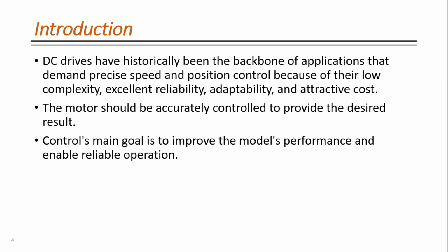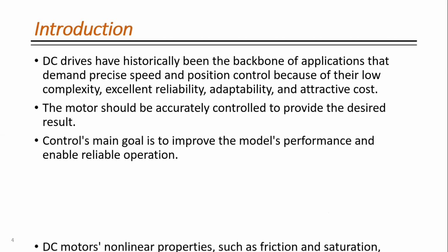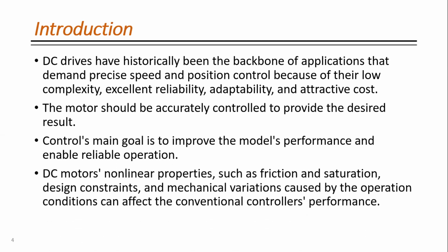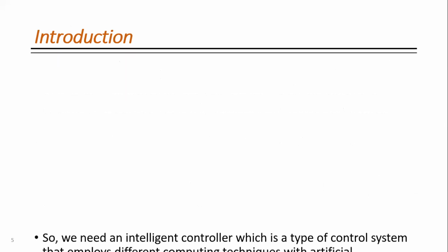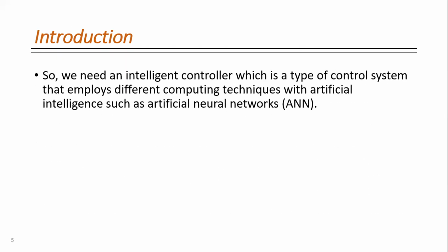A major problem in applying PID to speed controllers is the nonlinearity effects of the DC motor. DC motor nonlinear properties such as friction, saturation, design constraints, and mechanical variations caused by the operation conditions can affect the conventional controller performance. So we need an intelligent controller, which is a type of control system that employs different computing techniques with artificial intelligence, such as artificial neural network.